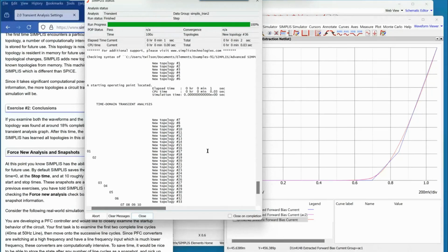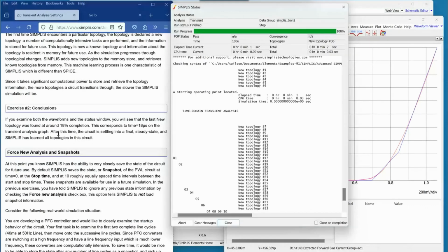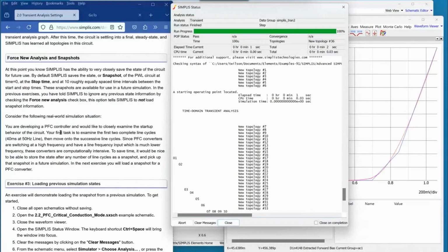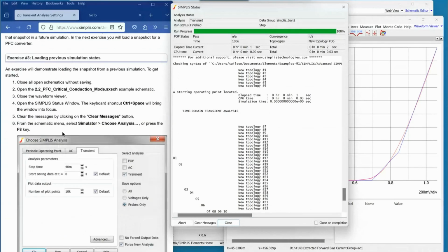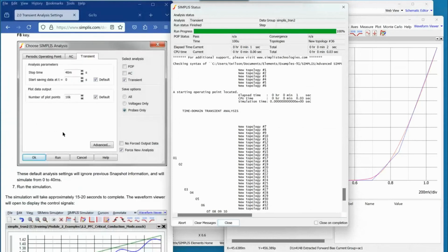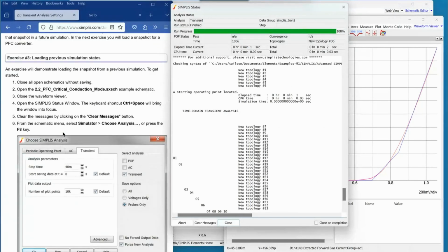Another possibility would be a classic logic gate where by mistake, through several paths, an inverting signal is going back to your input. And so you end up in a loop where you will never get a correct state to start out. One example that would not yield a starting point would be to put an inverter and put the output of the inverter back to its input. Because it allows instantaneous switching, you will never find any starting point. Right.